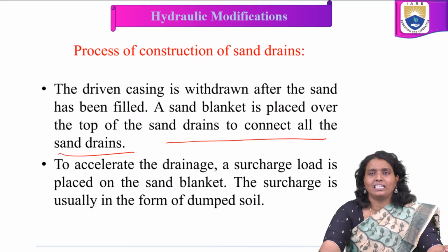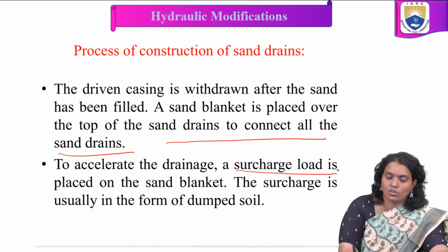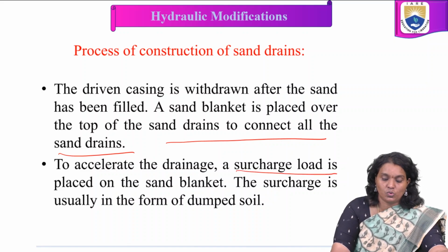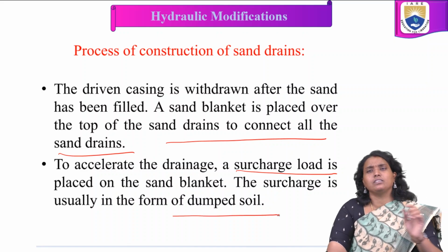To accelerate the drainage, a surcharge load is placed on the sand blanket. The surcharge is usually in the form of dumped soil.